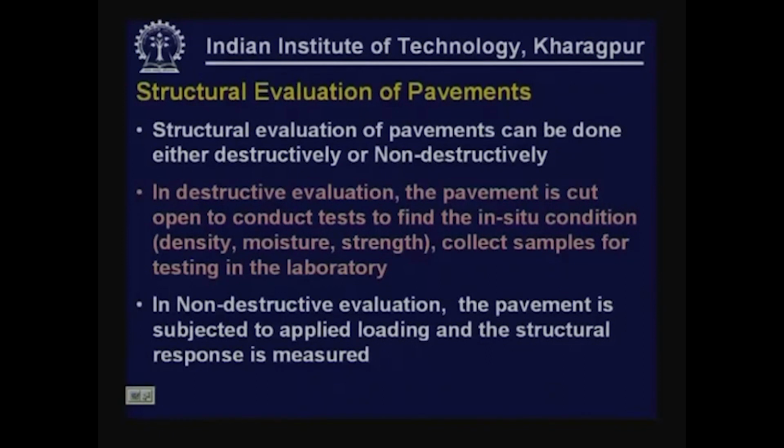On the other hand, in non-destructive evaluation, the pavement is subjected to some applied load and the structural response is measured. The destructive testing is normally very difficult. You have to cut open the pavement at a number of locations. You cannot go on excavating the pavement. Of course, if you do not have any equipment capable of carrying out non-destructive evaluation, that is the only thing that you may be doing. You may carry out only destructive evaluation. But if possible, one should go for non-destructive evaluation, in which we apply load and measure the structural response of the pavement.